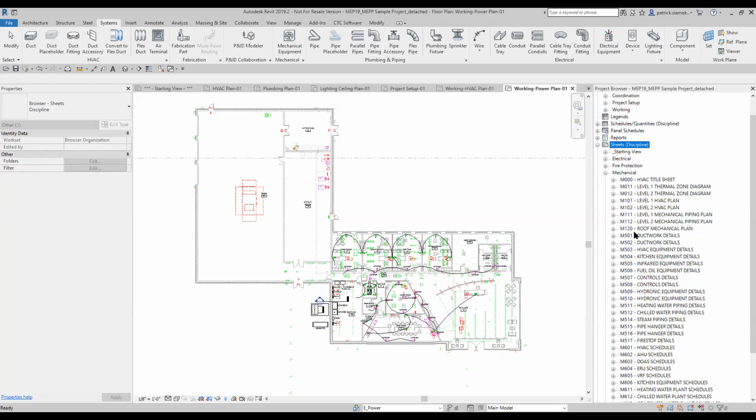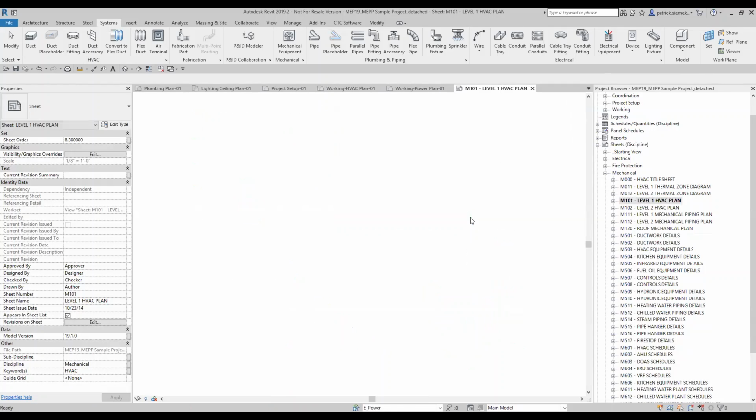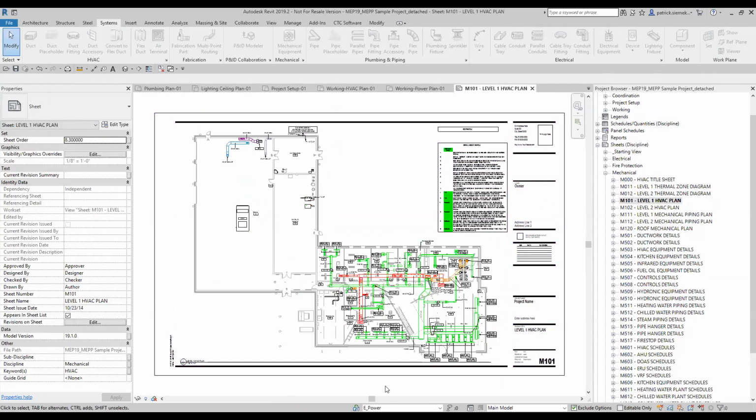So when a project starts, you just set up the scope boxes, you start working in the working views, annotate in the construction document views, and then finally, once you go back to your sheet, those views have already been placed based off of the location of your project. So as we have here, we got our sheet in place with a title block, having our viewport in the middle, which was our construction document view, and a couple schedules that come along with our item.